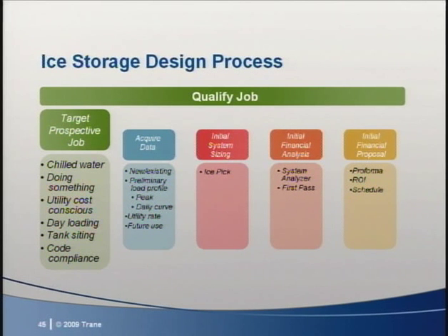Having building off time, or at least reduced loads at night, as well as a place to site the ice tanks is also very important. Finally, many owners would prefer air-cooled chillers, but local or state codes may limit the allowed system capacity. Some codes, such as California Title 24, have an exception for systems with energy storage. Or the addition of ice will allow the same capacity chillers to serve a much higher peak load.